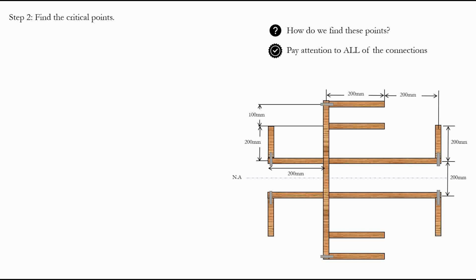Also, what we know is that as we go towards the web, so you move from here and you move towards the web, again, like from the flanges to the web, you are contributing to the shear effect in the web, right? So meaning that here, at this point, what is our shear value? The shear stress value here is 0. Why? Because there's no plane. There's no other plane. So we only have one plane, right?